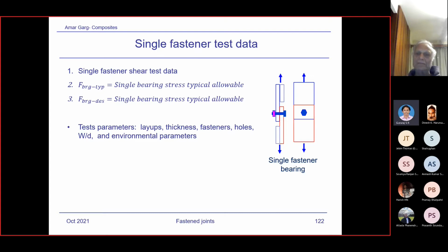Sir, you told us it is dependent on the direction of loading also, so at each location it will be different. Does this procedure account for various possible loading conditions? Oh yes, various load cases are analyzed. There are thousands of load cases in the aircraft structure. Then there's a load sorting when you are analyzing. Finally you will consider that there may be only 5 or 6 critical load cases out of thousands of load cases. It's a big process.